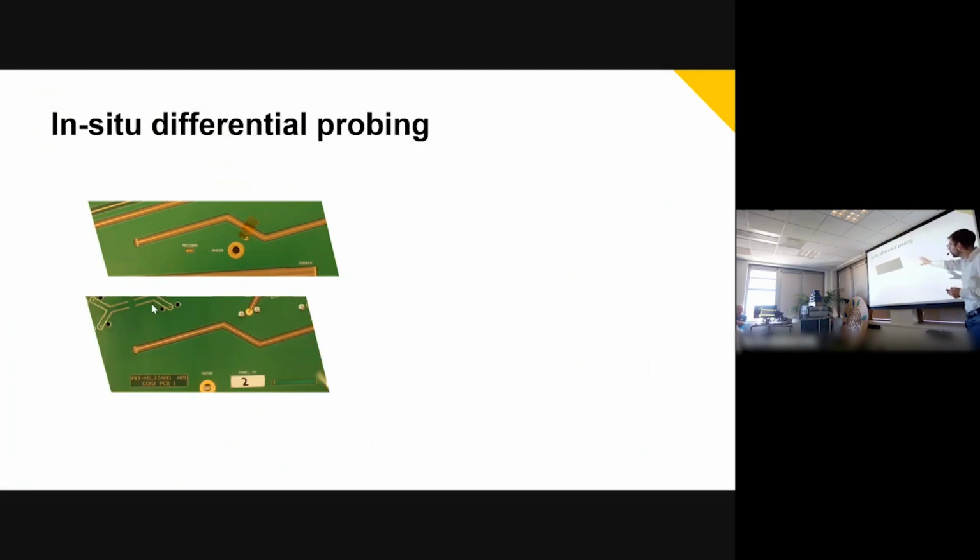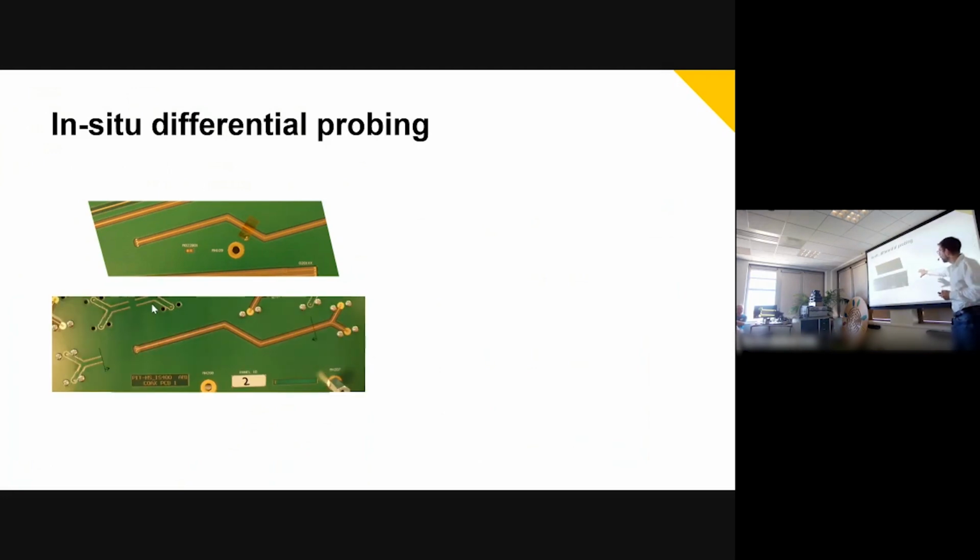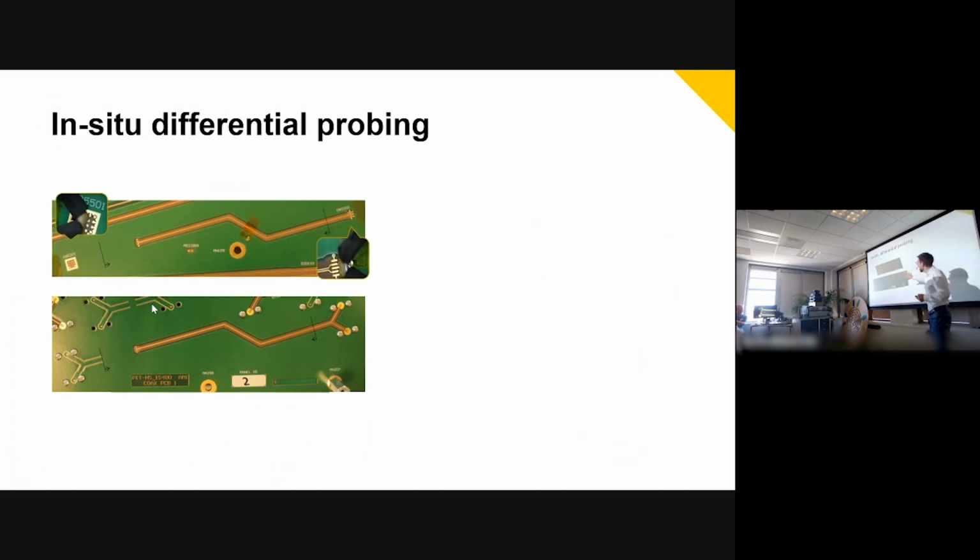And to know it, we duplicated this and we fitted it with a coaxial fixture. So that's our reference truth. And we also put some more real life connections to it. So here, this is a BGA field with 2 adjacent pads. And these are rectangular pads for example, board-to-board connector.